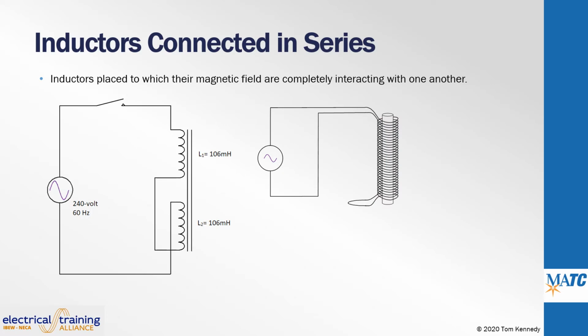If two of the same inductor coils were connected so that the magnetic fields overlap 100% and oppose each other, the opposing magnetic fields will not develop counter-electromotive force. The applied voltage polarity connected to the inductors is in opposite directions, so the coefficient of coupling of the magnetic fields becomes subtractive. When magnetic fields of inductors are placed so the direction of the field flux is opposing, the inductors are considered differentially coupled, or the magnetic fields are subtractive, and the difference is all that remains to provide CEMF to oppose current. In this example, the coils are of equal value and the magnetic fields are 100% coupled.